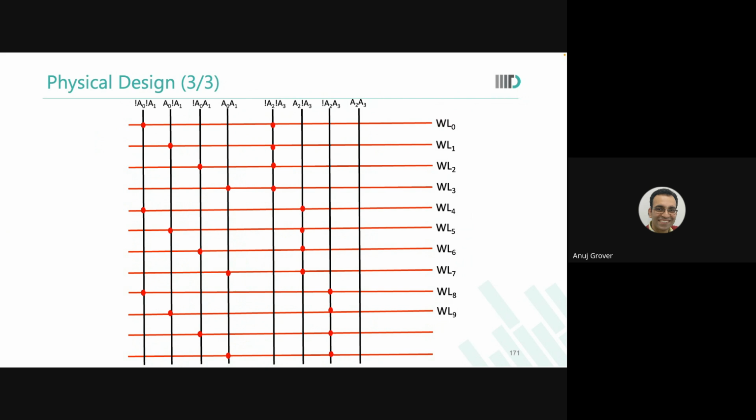Now we want to start mismatch, and you know that mismatch is already a problem for SRAMs. We saw those 60 cells and we saw that if the sigma variations are 3 sigma, then there is this kind of impact on stability, this kind of an impact on writability. If it is 4.5 sigma, things simply go into a different range altogether, and so on. So you already are struggling with mismatch. You do not want any additional source of variations into your system. That is why, as much as possible, you will try to avoid N well proximity effects impacting any additional delays in your system.